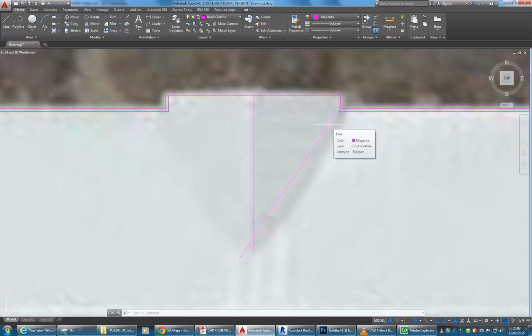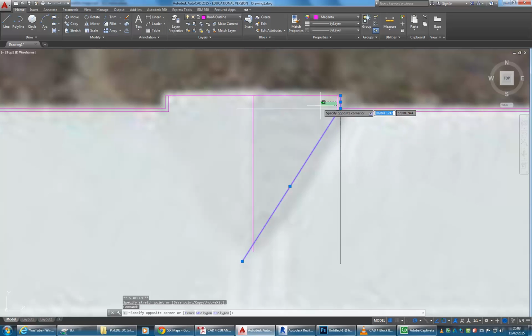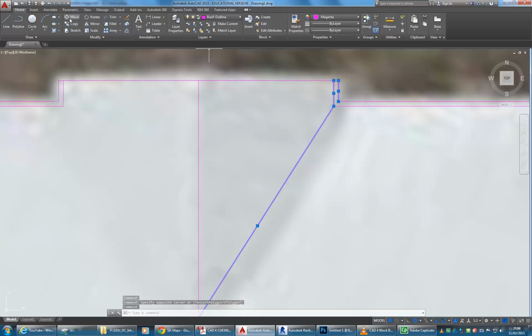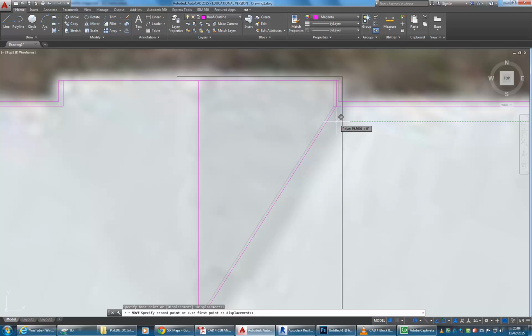Sorry, oh yeah, so this roof, it just doesn't follow that because the roof's a different pitch. All the others will be 45, but it's not worth setting the angle just for this one. And so there, what you could do though, well, I can see maybe just by adjusting that line a little bit, it'll be closer to the angle that it should be. And then the other thing is, if I get these two lines, and then use move, just bring them over slightly.